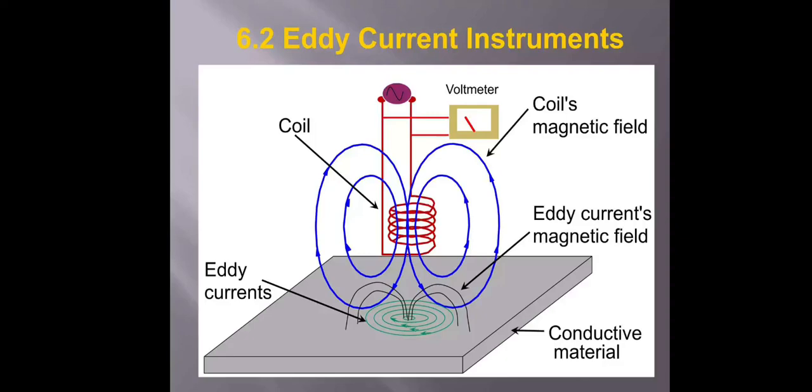As the picture shows, the eddy current test works on the basis of electromagnetic induction. In this method, eddy currents are induced in the test object by bringing it closer to the alternating current carrying coil as shown in the figure. These eddy currents are normally parallel to the coil winding. The defects in the test object change the impedance and the direction of the eddy current, causing changes in the electromagnetic field. These changes affect the inspection of the specimen, and the voltage is monitored to determine the presence of defects.